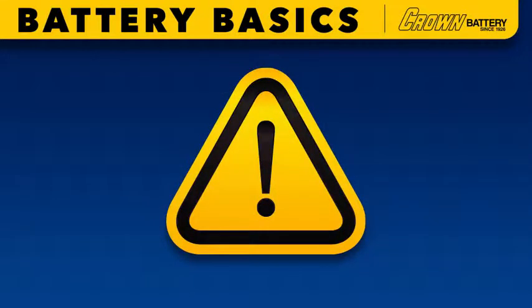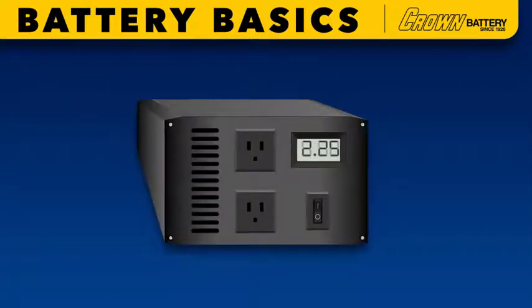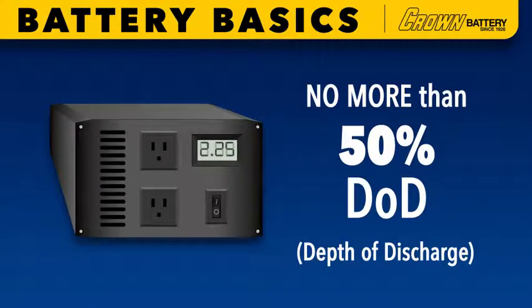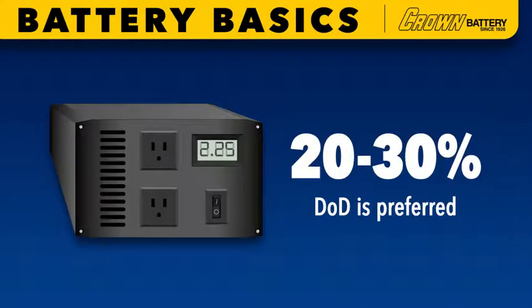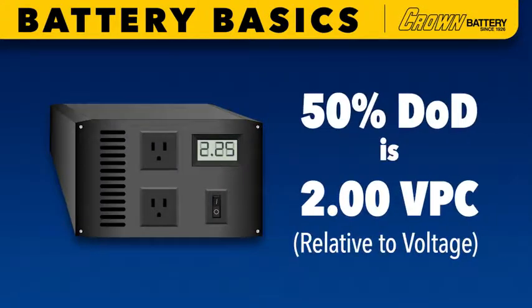Again, the voltage and timer set points reviewed here are suggested settings and should only be considered a starting point, assuming the following, especially important criteria. First, the low-voltage battery cutout or disconnect of your system's inverter should be programmed to allow no more than 50% depth of discharge, or DOD. With that being said, a 20 to 30% DOD is preferred, which would also extend battery life as well as simplify maintenance procedures. Relative to voltage, 50% DOD is 2 volts per cell.